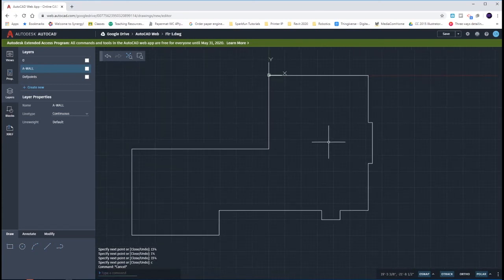All right, we talked about offsetting. We have 2 different offsets. A couple of these walls will be at 4.5 inches and the others will be at 6.5. This wall here, we're going to have to offset twice: one at 4.5 inches, the other one at 6.5 inches, in order to get both the garage and the normal wall thickness.